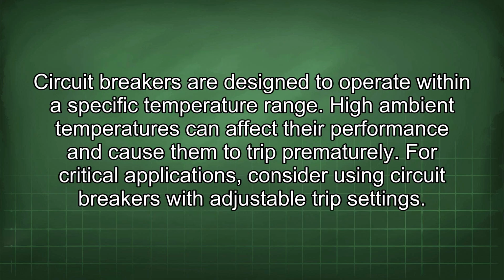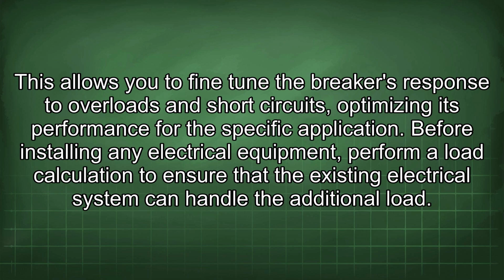Circuit breakers are designed to operate within a specific temperature range. High ambient temperatures can affect their performance and cause them to trip prematurely. For critical applications, consider using circuit breakers with adjustable trip settings. This allows you to fine-tune the breaker's response to overloads and short circuits, optimizing its performance for the specific application.